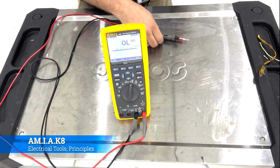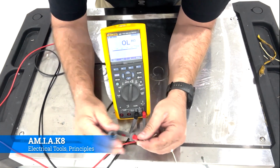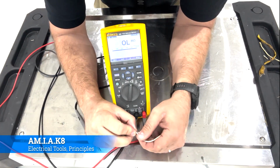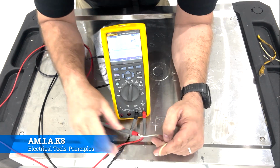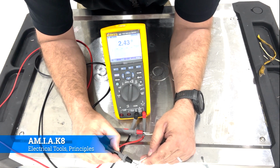Okay, so let's go back to the resistance measurements. It's going to be the most common way that you use pretty much any multimeter, which is just checking continuity of 2 different wires. So here we have a wire that we have good continuity for. You see how low the resistance gets?